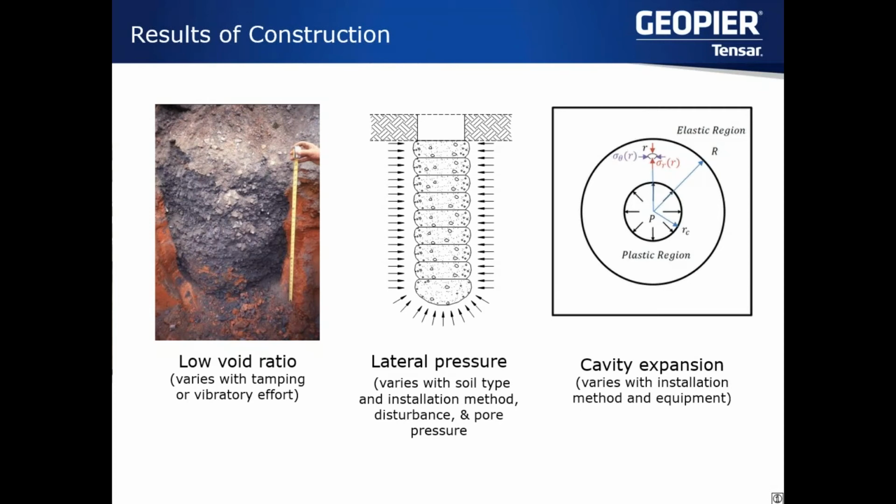So as I was saying, we rely very heavily on confinement, particularly in the case of aggregate piers. And we also showed that we see an improvement factor of the surrounding soils, and that's due to the ramming action of the tamper forcing the aggregate into the surrounding soil. Now with rigid inclusions, as I mentioned just now, typically those are displacement techniques. And because of that, the improvement usually isn't as dramatic. And often because we're doing these in very poor soils, very soft soils, there quite frankly really isn't much to improve. So in those cases, we're strictly dealing with stress transfer.